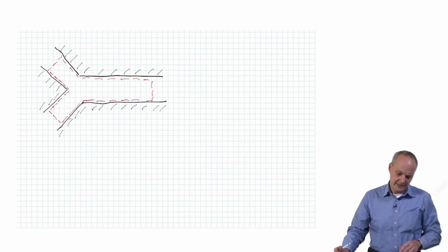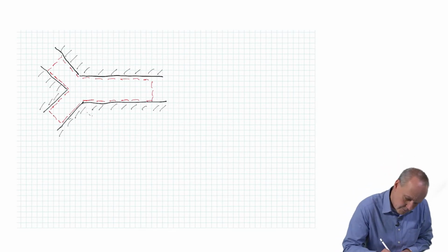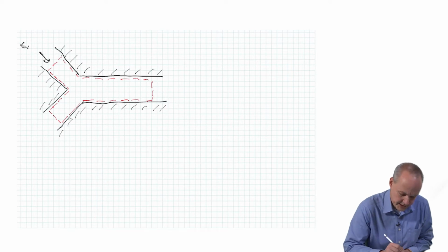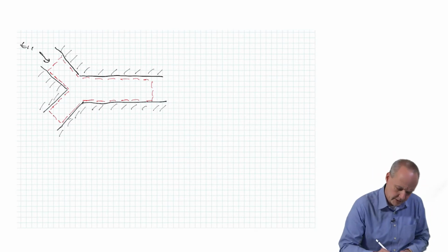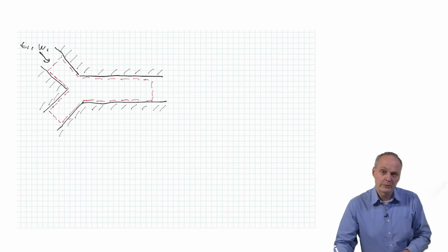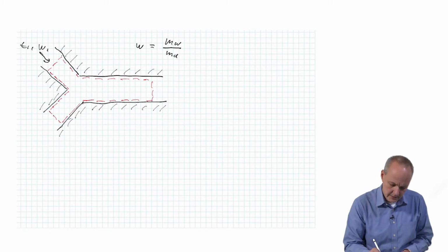And we're bringing in two airstreams. One airstream, 1, comes with a temperature T1, and it comes with a certain amount of humidity. And I remind you, we had talked about the humidity ratio, W1. And again, what was W? W, the humidity ratio, is the mass of water divided by the mass of dry air. Okay, so that's a reminder.